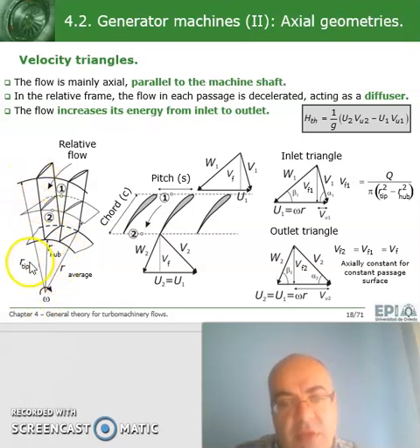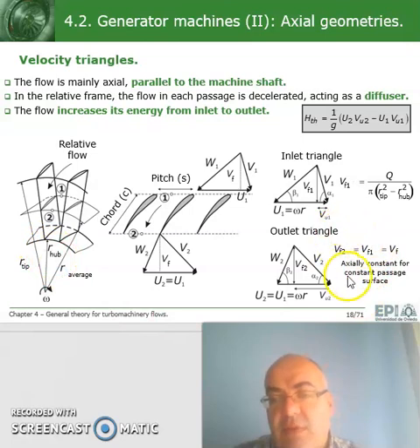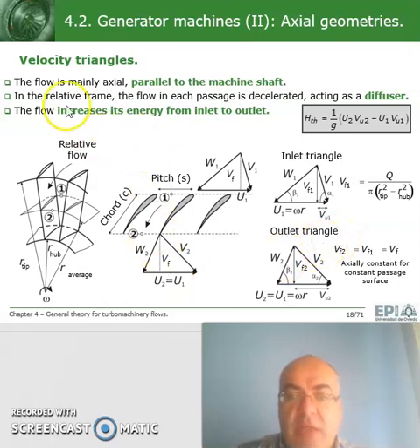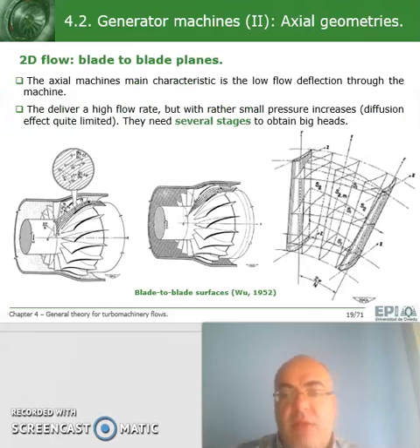And second feature, if we don't change the axial variation of the surface, so tip and hub radius are kept constant, then the height of the triangle is also kept constant. All those ideas on this slide are the 1D theory summarized here by the Euler equation, and those can be expanded and are done in the bibliography to the 2D study.